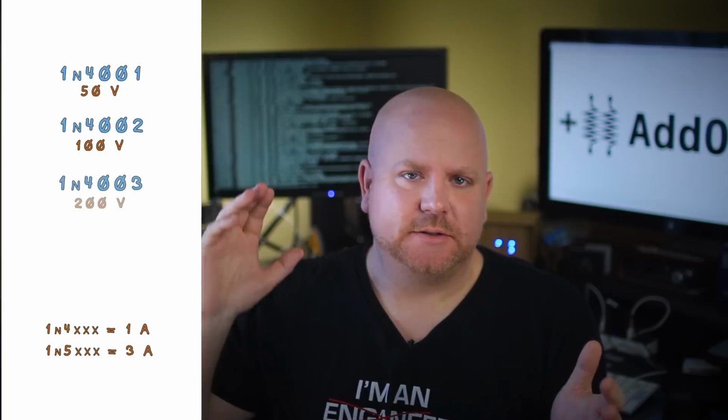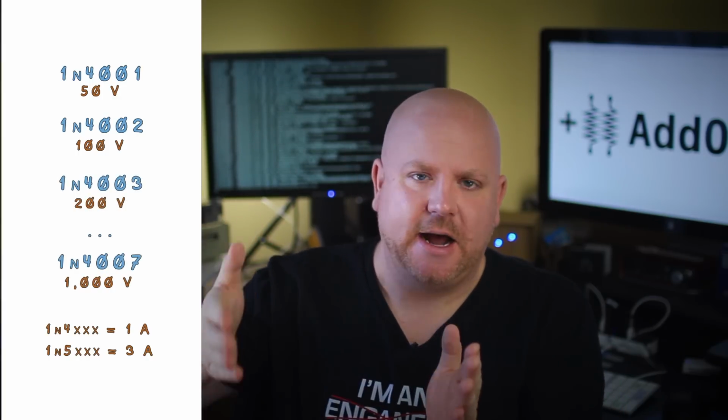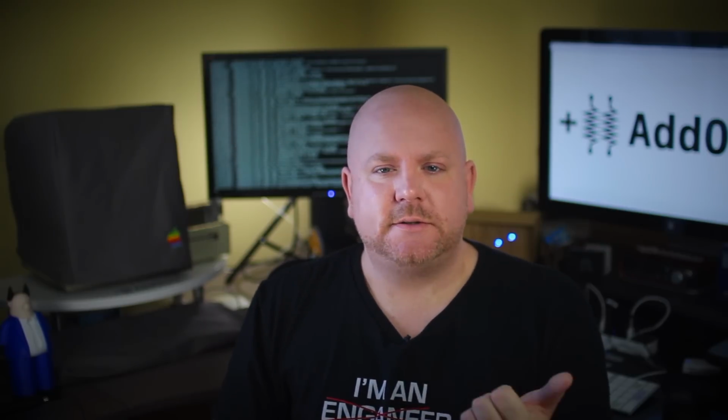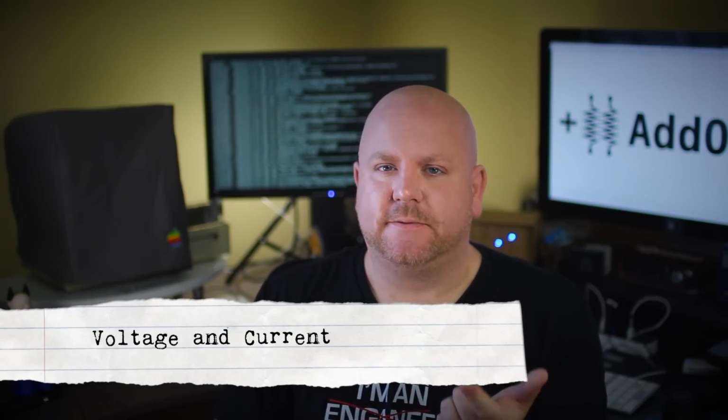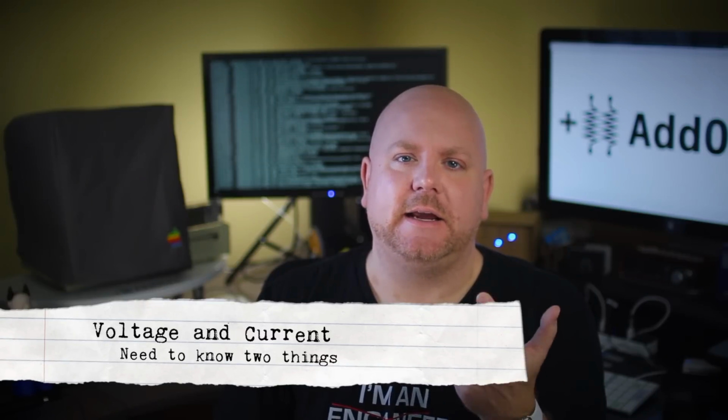Now there's a whole series of these diodes. It starts with a 1, goes up to 7. With each one of them, the specs are just a little bit higher and higher. If you want to pick a specific diode, you really only need to know two things: what's the voltage of the motor and how much current is flowing through it? With that, we can start to calculate or pick a diode.